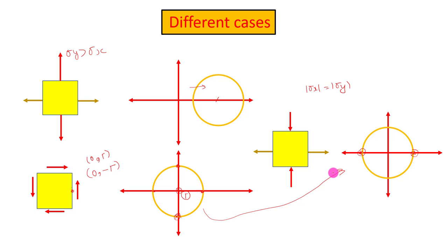So what's the unique thing about this case? In all the cases that we had discussed, at the point where shear stress is maximum, there was some normal stress present in the system. Now for this case, this is a principal plane and this will be your maximum shear plane.